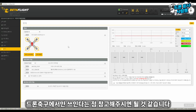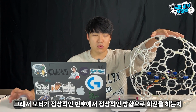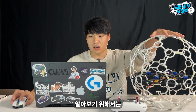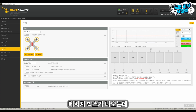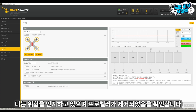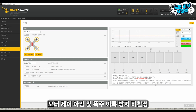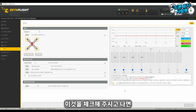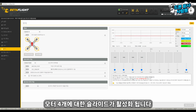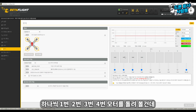To check if the motors are rotating in the correct order and direction, a message box called Motor Test Mode Arming Notification appears at the bottom stating, I am aware of the risks and confirm that the propellers have been removed. A checkbox labeled Motor Control, Arming, and Disable Runaway Takeoff Prevention appears, and once you check it, the sliders for these 4 motors are activated. We will try turning on the motors one by one.